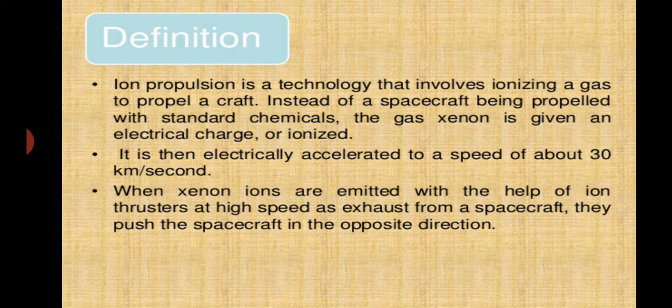In some spacecraft, they use chemical engines. However, ion engines work differently than chemical engines. Ion engines take very small amounts of gas and accelerate it to very high speed, unlike chemical engines, which take large amounts of gas and spew it out at low speed. This means that an ion engine uses a lot less fuel.